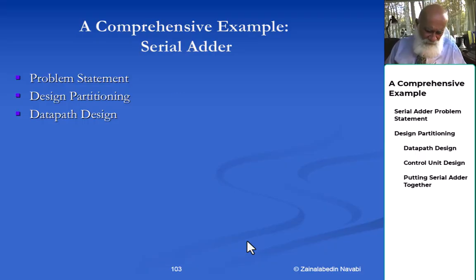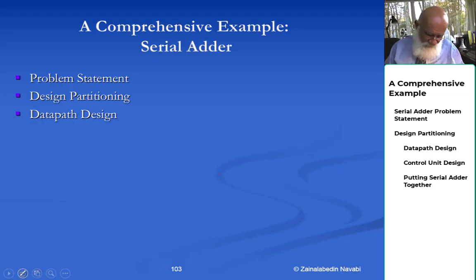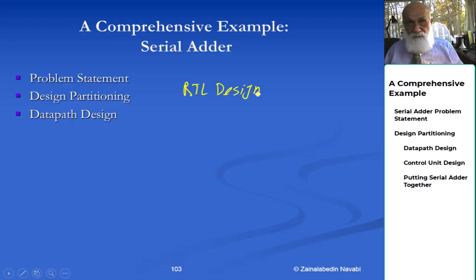When you are doing an RT level design, RTL design, you first start with the problem description, and then you decide, okay, I need some data components.